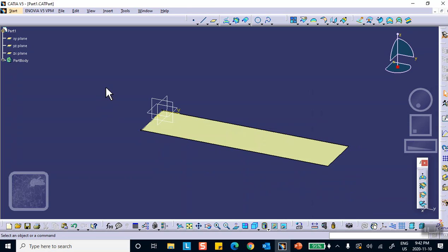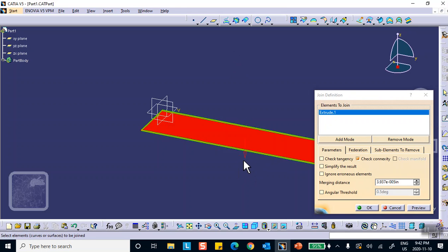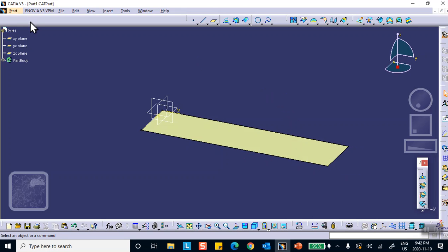All right. Let me go back here. When you mesh this thing with shell elements, the elements have a local coordinate system which is actually opposite to the direction of the normal. So what I want is for the normal to my shell elements to be upward. That being the case, I'm going to flip this. Remember, the direction of the z-axis for the local element is opposite to the direction of this joint. Okay, so there we are.